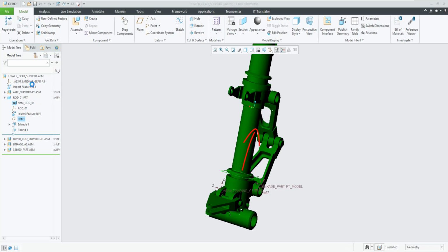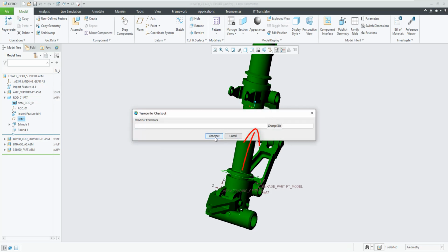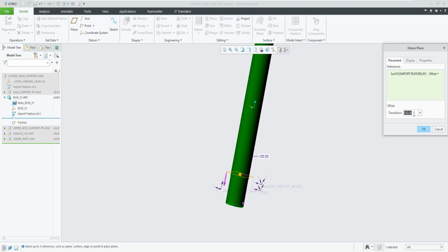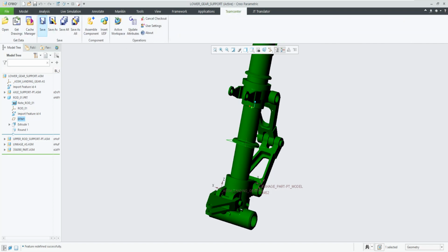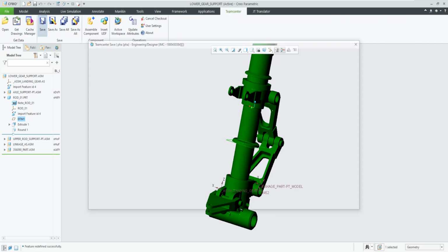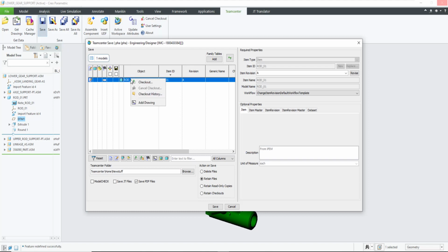What happens when the Creo design is changed in its authoring tool and saved back to Teamcenter? Remember that the Creo design is directly reused by SolidWorks, allowing the SolidWorks parent assembly to maintain any constraints that were made against the Creo models. In this case we're simply moving the feature that was used in the SolidWorks mate.